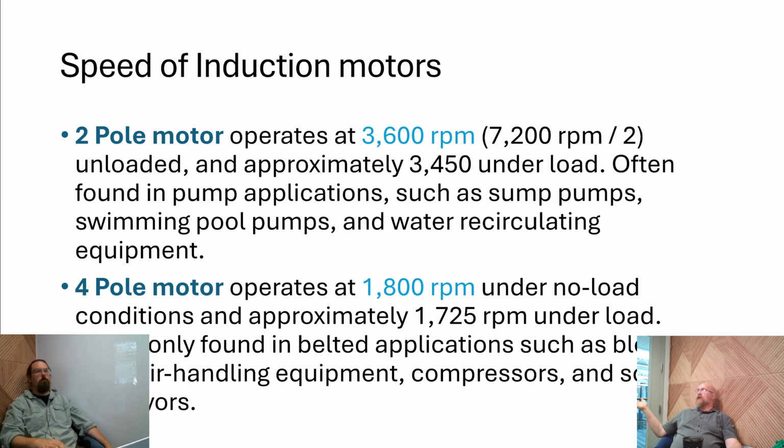The synchronous speed is never achievable. There's still a little bit that causes slip in there because of the friction due to the bearings, and we'll get to the slip. We're talking a lot about it, but you've got to get through this stuff in order to understand what's actually subtracting from it.